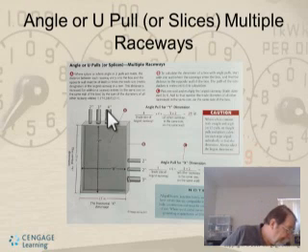So you take 6 times 3, plus the other 2-inch conduit or raceways, which gives you 22 inches. So the width is 22 inches and the length is 29. So you have to find a box that fits that. They usually have 24 by 30s, 32, something like that would be good enough to fit that.